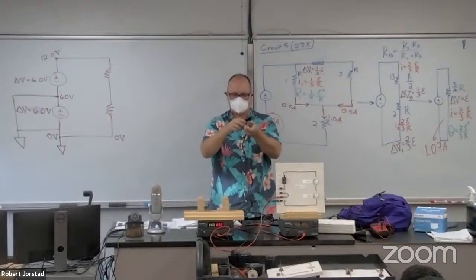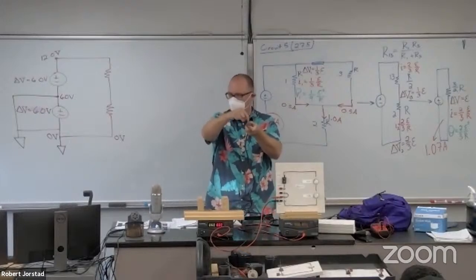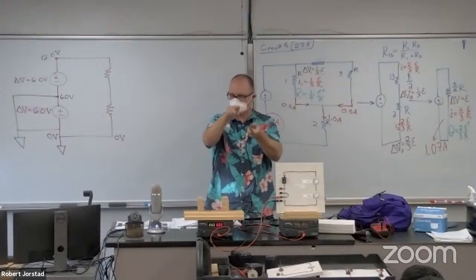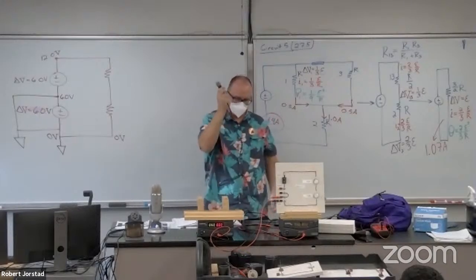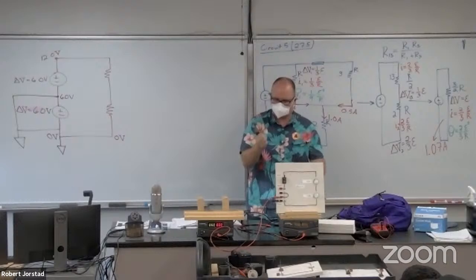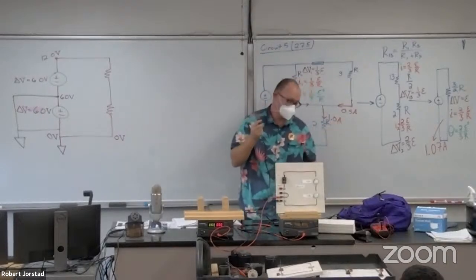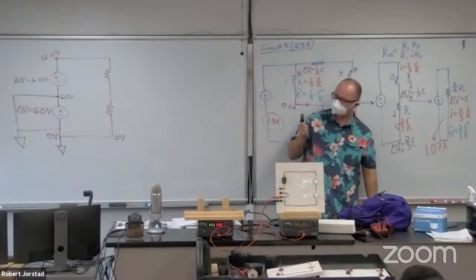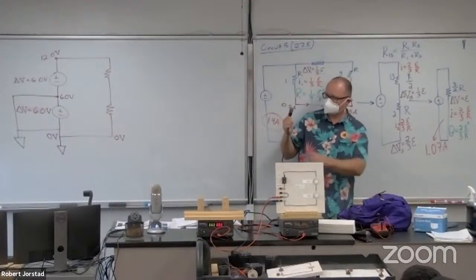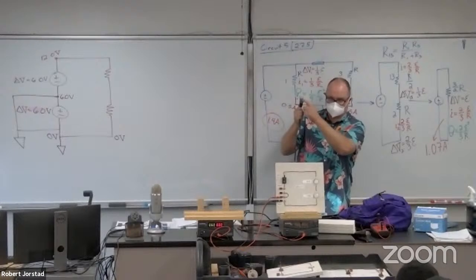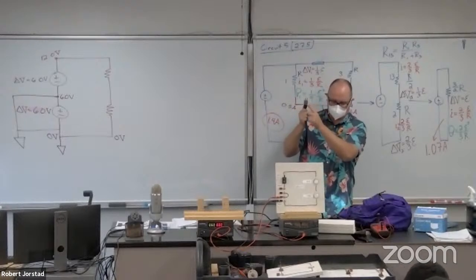Some of them used to have the grounding. You'd literally bolt this onto the centerpiece of the electric socket. There's a screw in the center. But now this is generally not a safe thing to do. Sometimes these are called death plugs. I don't know why. Don't do this at home. All right, so the idea now is we're going to disconnect one of these power supplies from ground.